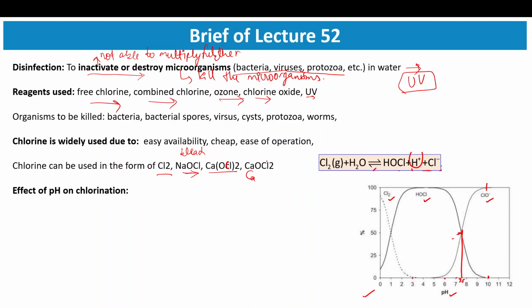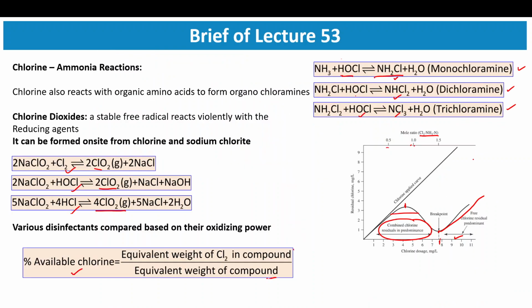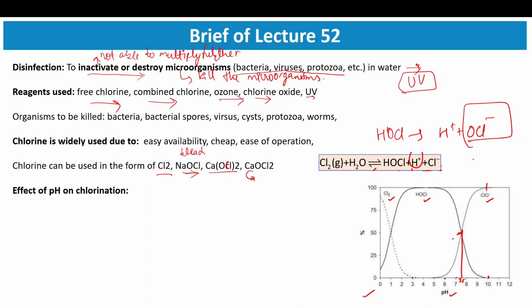Now, what happens here is that when Cl2 goes into water, it forms HOCl plus H plus and Cl minus, and this HOCl further dissociates into H plus and OCl minus. Basically, this is the compound which is responsible for the water disinfection.